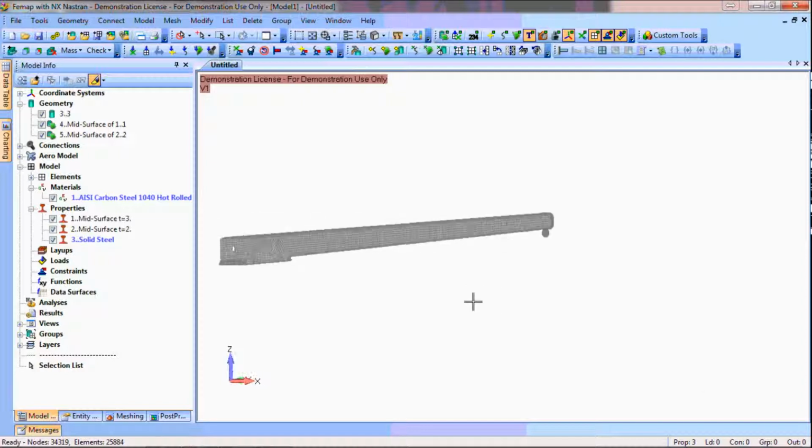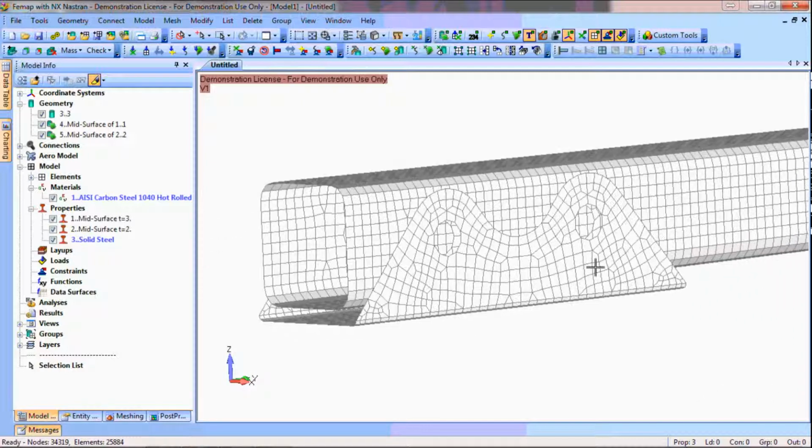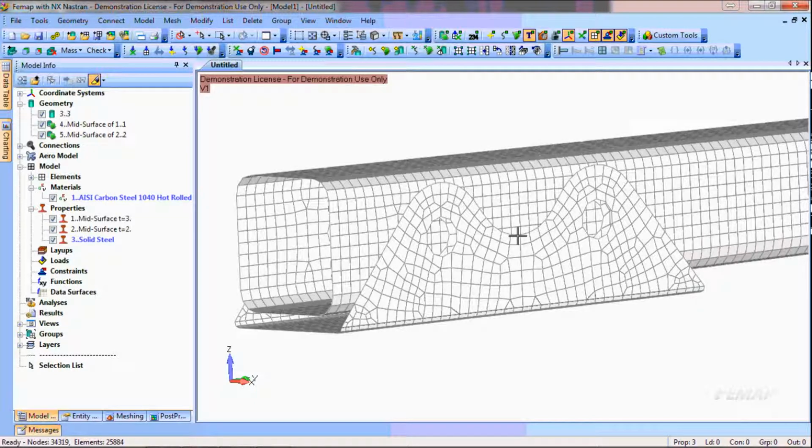Now if we come back up to this end, I need to connect the beam and the end plate, and often what happens in finite element models is the bolts get connected to the edges of a beam or the edges of a hole. Now this is not ideal.